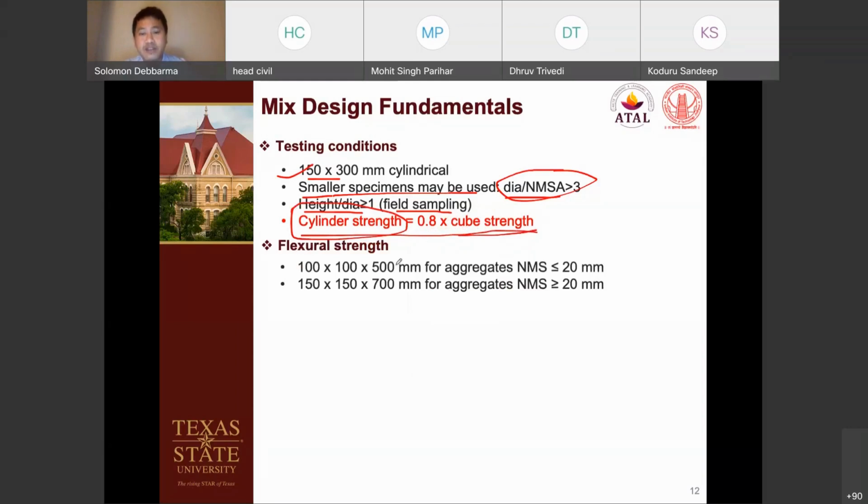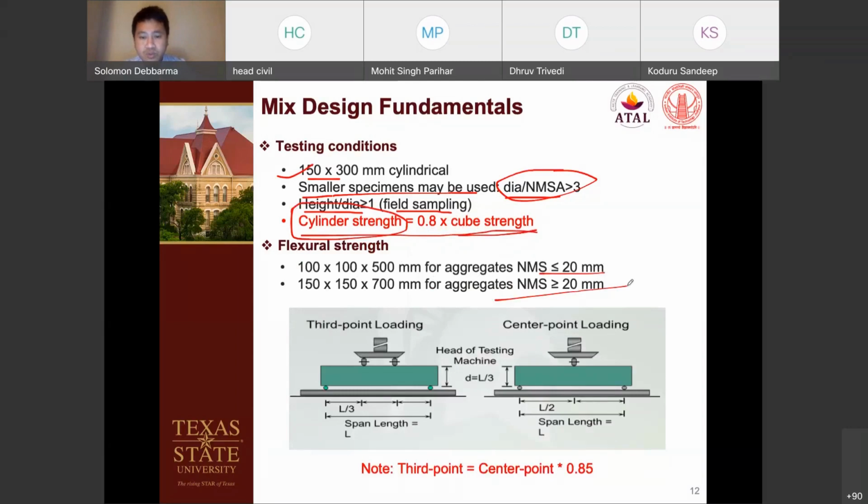And yes, the flexure strength is also very important. So this is again the wall effect. And usually in the past, concrete pavements have been designed based on the compressive strength, but we should understand that concrete pavements should rather be designed based on the flexure strength, because concrete pavements fail purely in bending, right?